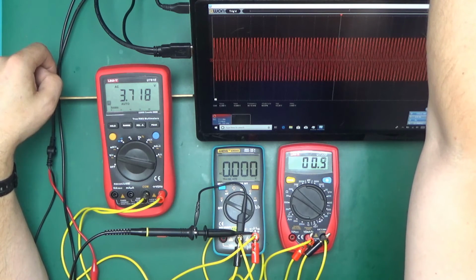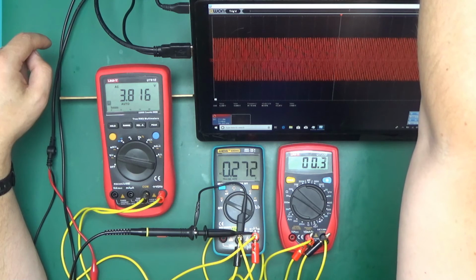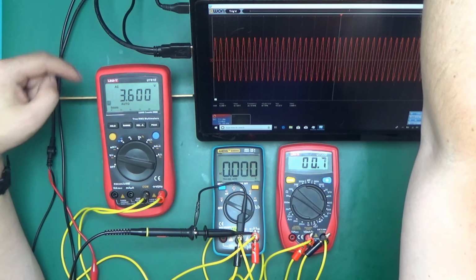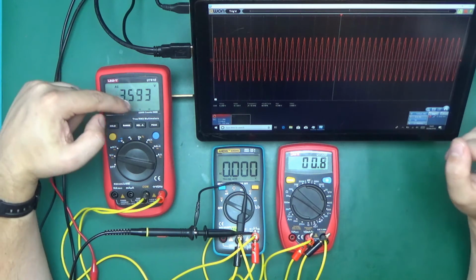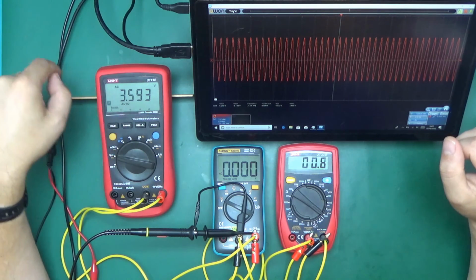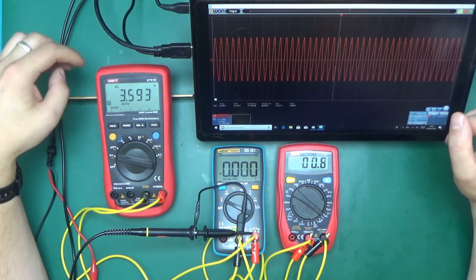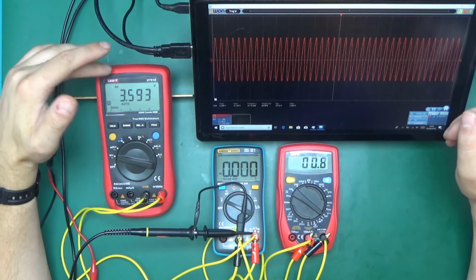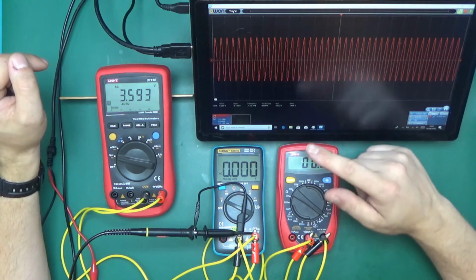That's 40 kilohertz, but it's starting to read a little bit high. Let's go stupidly high. 60 kilohertz, 22 kilohertz, jump to 3.6 volts. So let's call that quits on that one. So instead of actually dropping the voltage, the measurement, it bumped it up. But nonetheless, it's a better frequency range on this one compared to the AN8002. But that's not the problem.